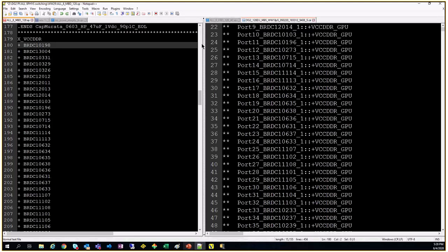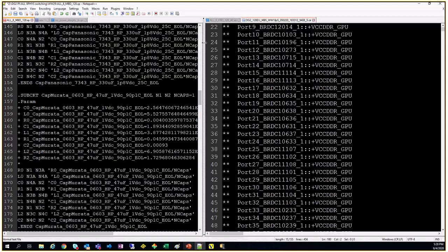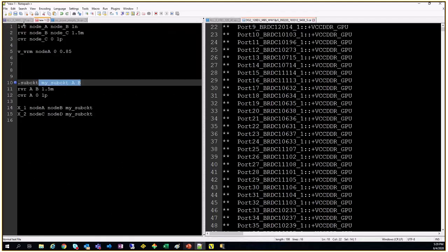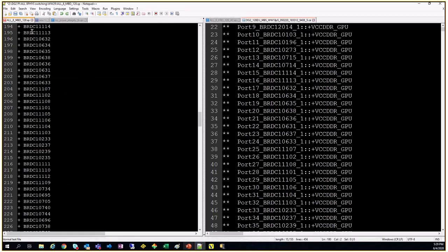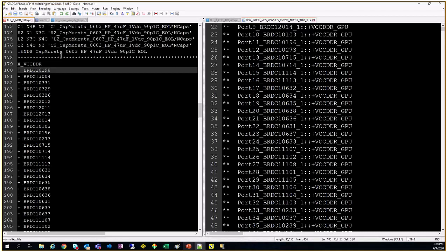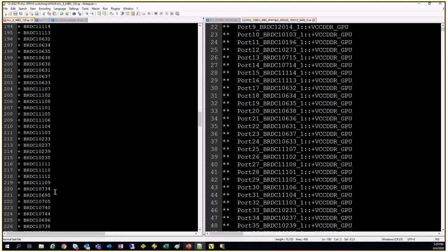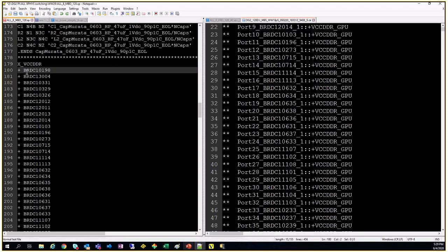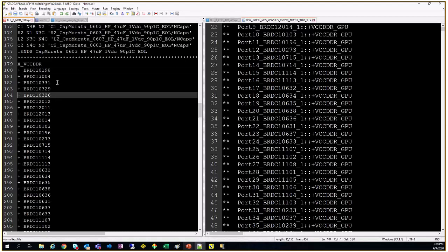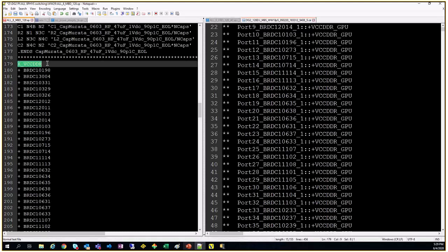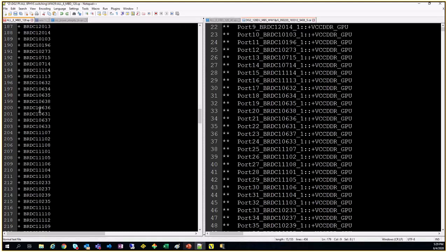But due to the sheer number of ports, it goes to the next line for ease of reading. Because you want to make it part of the same command, you write this plus over here. You're telling it that it is not another command; it is part of this command only. This subcircuit only I'm calling, but I am going to the next line to make it easy.